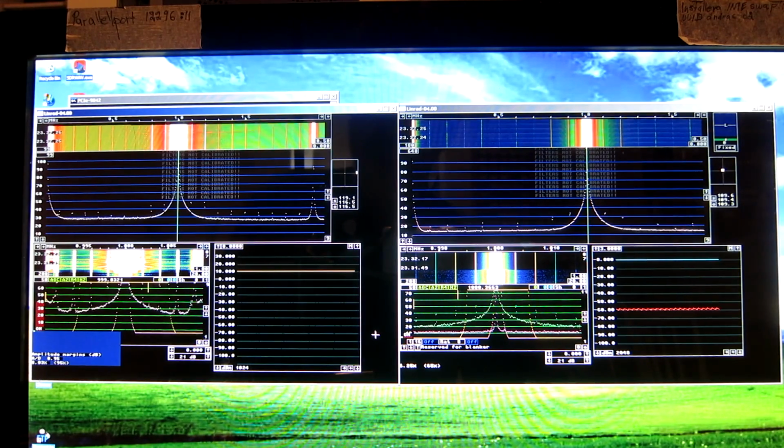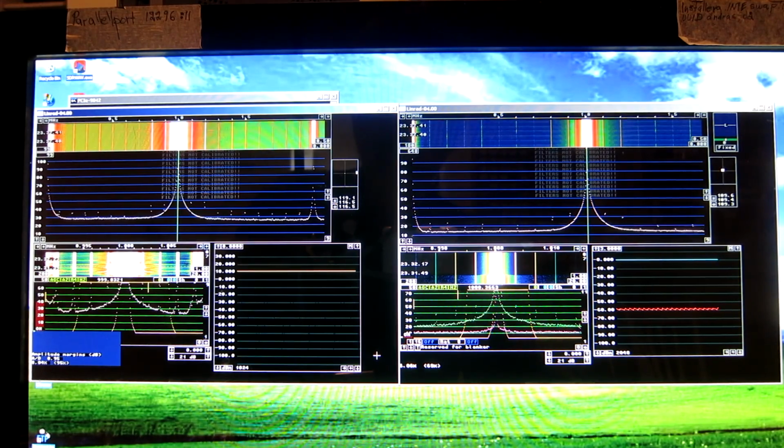15 as compared to 12, that is 3 bit, should be 18 dB, but I only see 12 dB. I don't know the reason for this, but of course the noise floor is not only the ideal noise floor. There are contributions from the input amplifiers and things that I don't know so much about. Anyway, there is a difference, but not very dramatic.